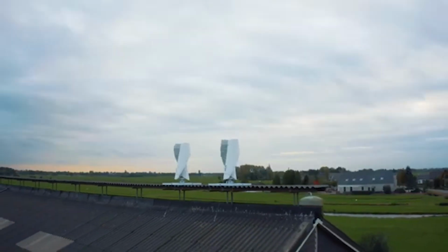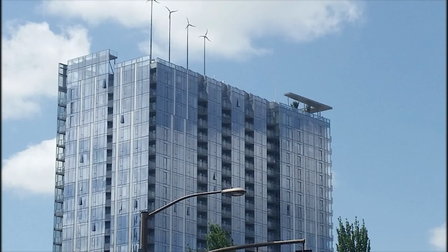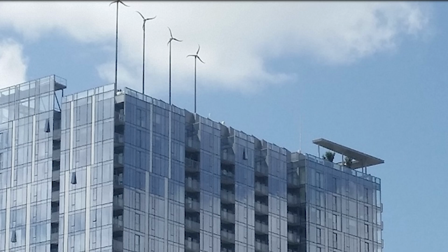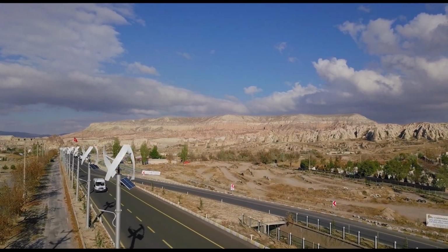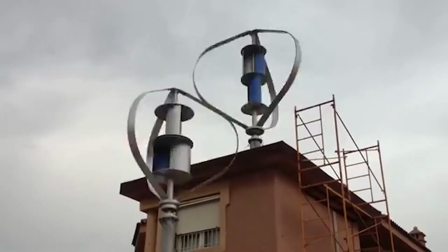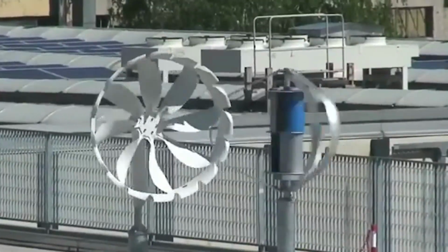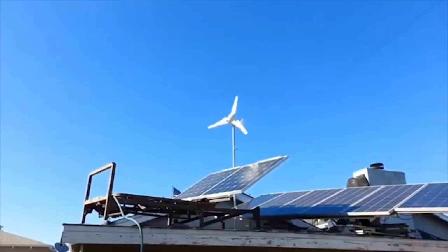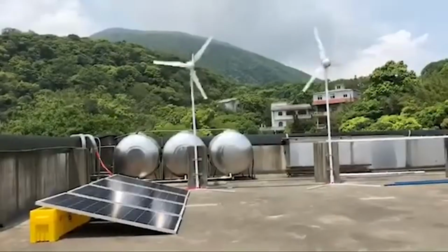For smaller clients, such as businesses, farms, and residential areas, small-scale wind turbines offer an opportunity to benefit from wind energy. Small-scale turbines are deployed in a wide range of locations at an elevation of between 30 feet to 140 feet. They can be installed on-grid, meaning tied to a central grid system, or off-grid for remote locations. However, because wind speed is slower and inconsistent at low elevations, small-scale turbines generate much lower power.